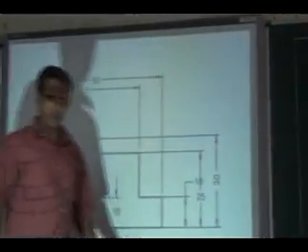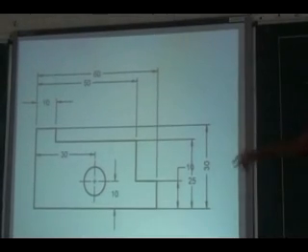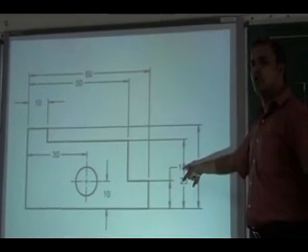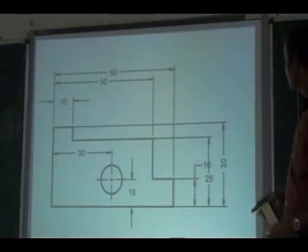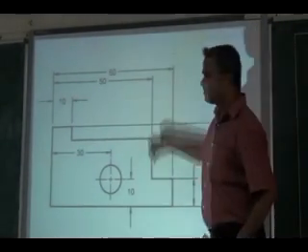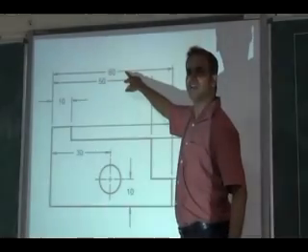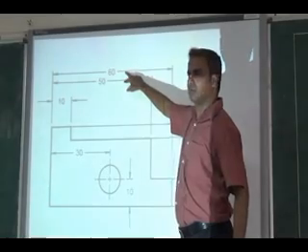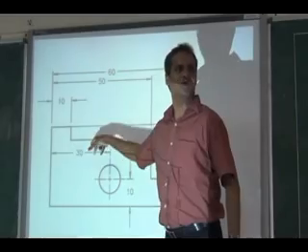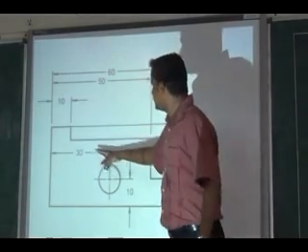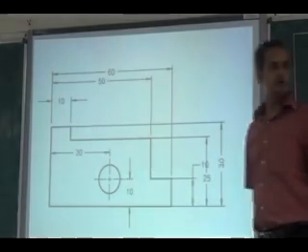You tell me what are the mistakes in this dimensioning. I have some mistakes. 10 is written over the line. It should not be. Right. What else? You see, one by one. 60 and 50, the gap is very small. It should be 10 mm. Then 30 is inside. You should take 30 outside. Right. 10 also you should take outside.